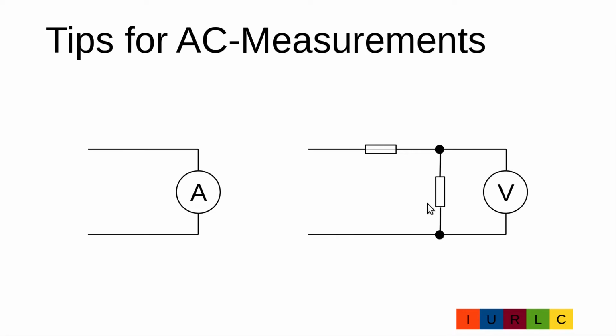The current sense resistor has a resistance depending on the current measurement range from some milliohm up to some 100 ohm. This low resistance here protects, similar to the short on the voltage measurement, against capacitively coupled signals on the measurement lines.